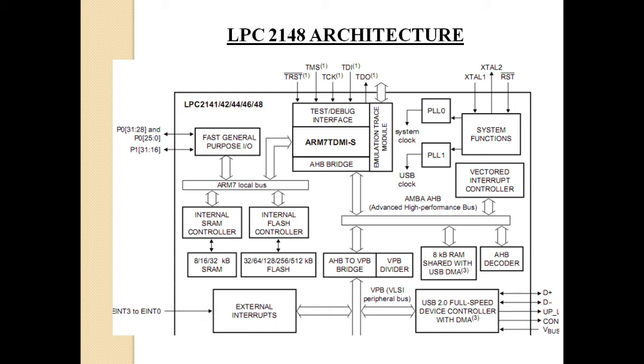In flash memory, bulk read and write of data is possible. That is why in your pen drive you are having flash memory. That is a main advantage, and you can perform the read and write using the normal 5-volt supply, right? And you are having more erase cycles, around 1 lakh erase cycles in this flash memory. So now you are using the flash memory for storing the program and RAM for storing the data, right?